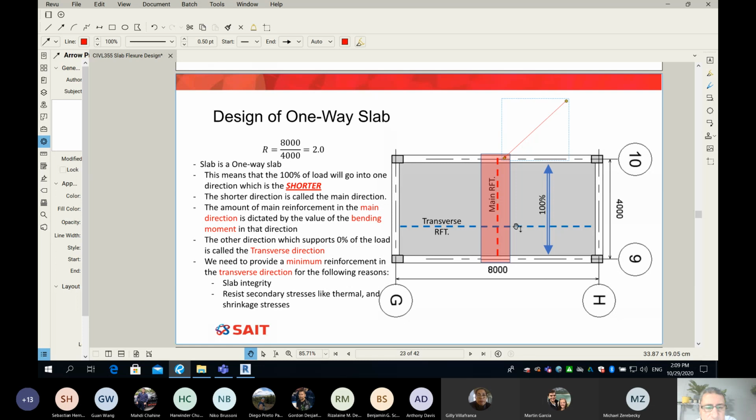Now I know some of you will say, okay, fine, so we found, let's say I need 5 bars per meter, like a 10 m every 200 mil. Okay, so what should I do? I'm going to put in this meter 5 bars. I'm asking you, what should I do with the next one? Leave it? No. If I leave it, it means I'm going to put 5 bars in this 1 meter and no reinforcement to the left and the right, right? Is that what you're saying? For sure, there is reinforcement on the left and right.